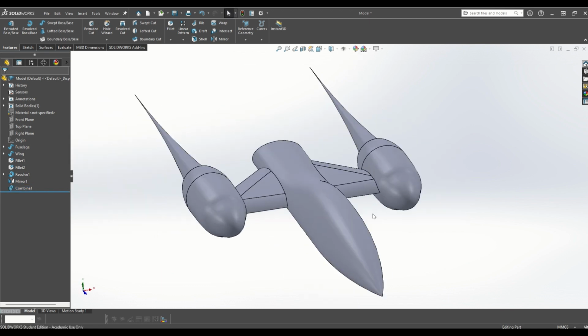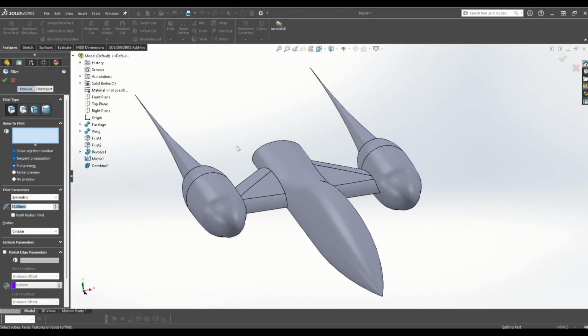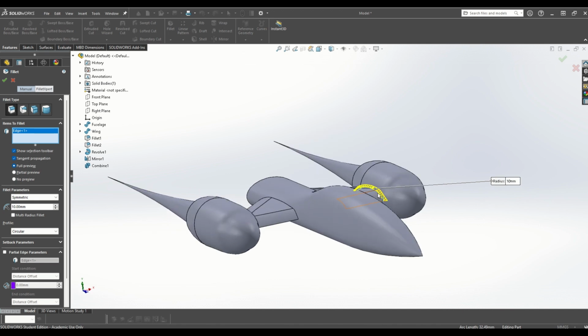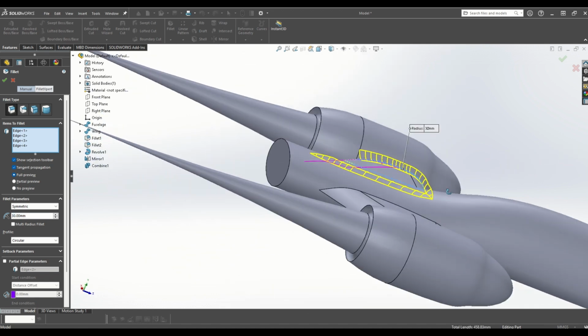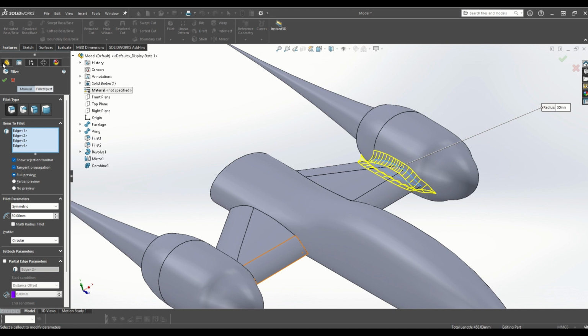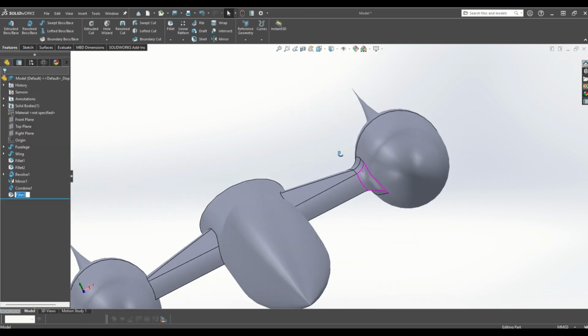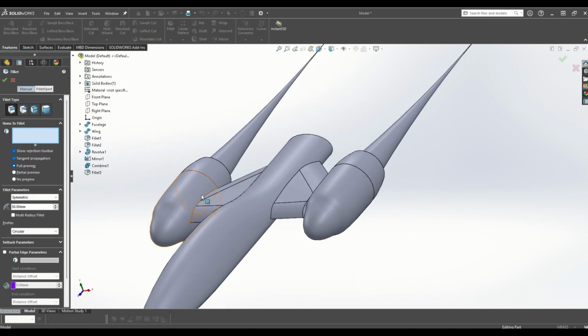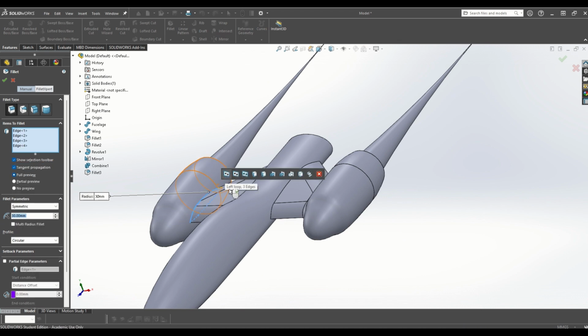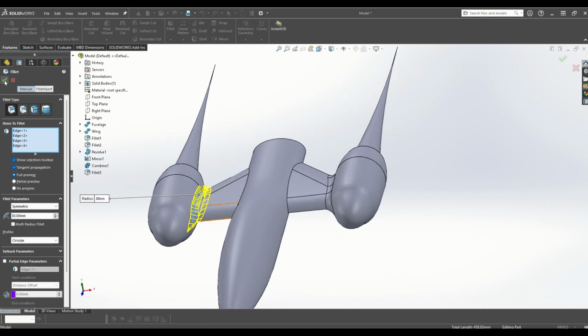Now what do I want to do? Okay, so I want to insert a feature here now, a fillet. So I'm going to click on this, and when I click on it, I have this option that loops around, that also includes this here, but it only does so when I click on it. So I'm going to click on that, and I want to loop around. I'm going to do this somewhat by eye, see what looks best to make them merge into each other in a real nice way. I'm going to say okay to that dimension there. Okay, I'm going to copy that on the other side. I could have actually done this before I mirrored. Probably should have, but that's okay. And I'm going to also use this to create this feature here and say okay.